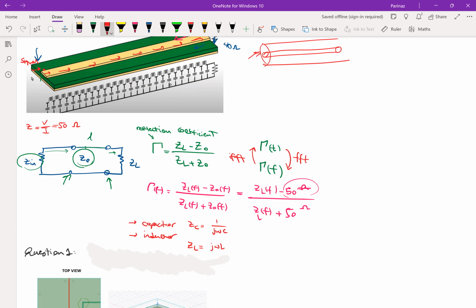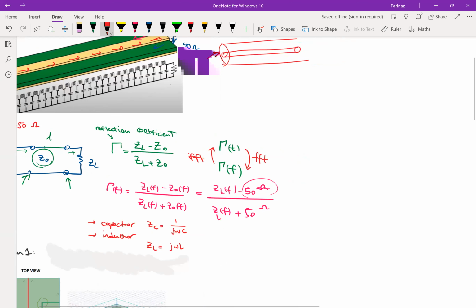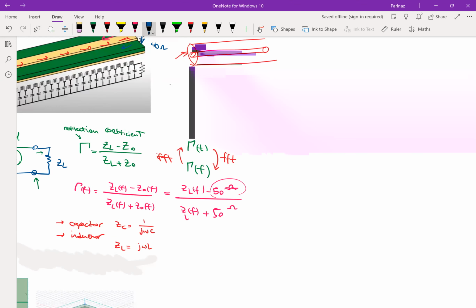Okay, so now whenever you measure an antenna, especially a narrowband one, or an RF device, you basically look at the reflection coefficient. Most of the time, you're looking at the reflection coefficient in the frequency domain. So ZL, gamma in the frequency domain, can be measured easily with what we call a vector network analyzer.